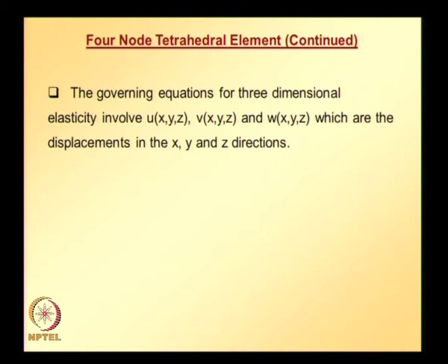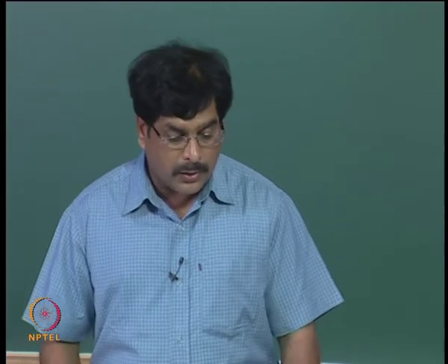The governing equations for 3-dimensional elastic problems involve u, v, w, which are displacements along x, y, z directions. 3 different trial solutions are therefore required. There are 3 unknown displacements at each node, 3 degrees of freedom per node.